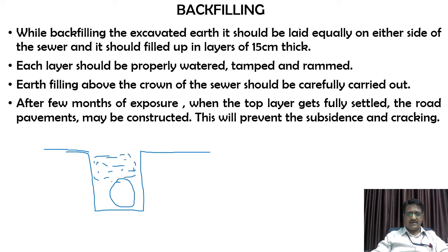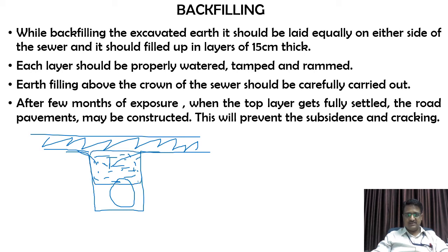If I don't provide this backfilling properly, and on top of that I construct a road, then in due course of time water may infiltrate. Because of this, the soil which is already over here can get compressed, and there will not be any support for the road for this particular width or section. Because of this, whenever the additional live load of vehicles is added, there is a chance of this portion of the road to collapse inside.